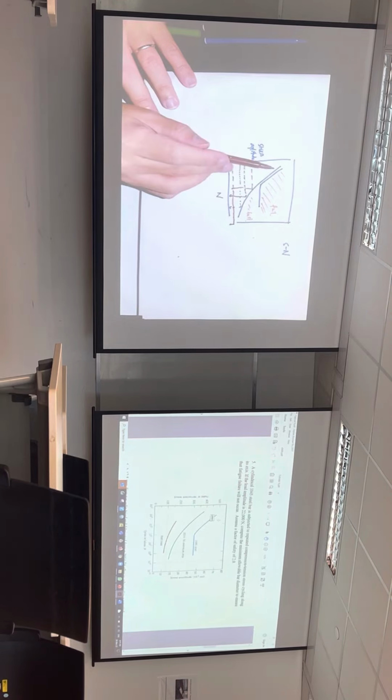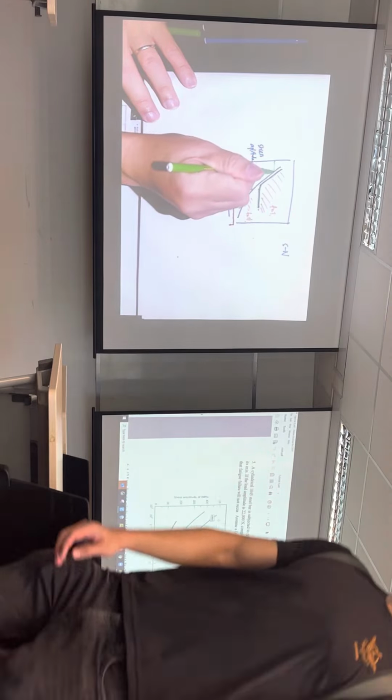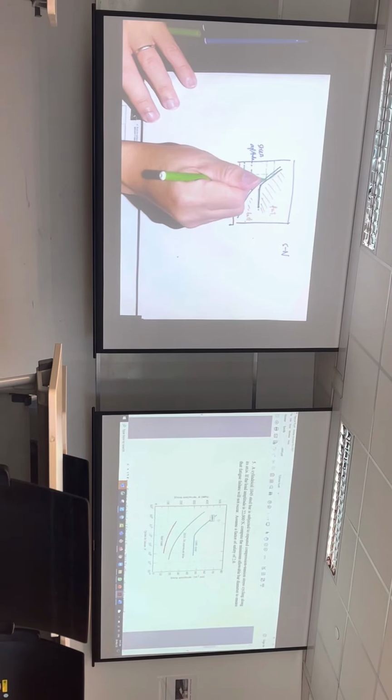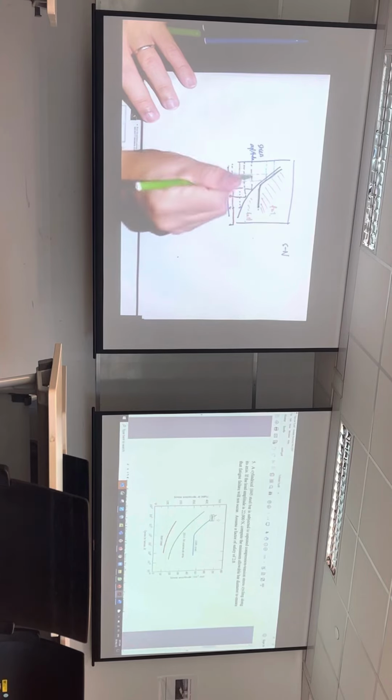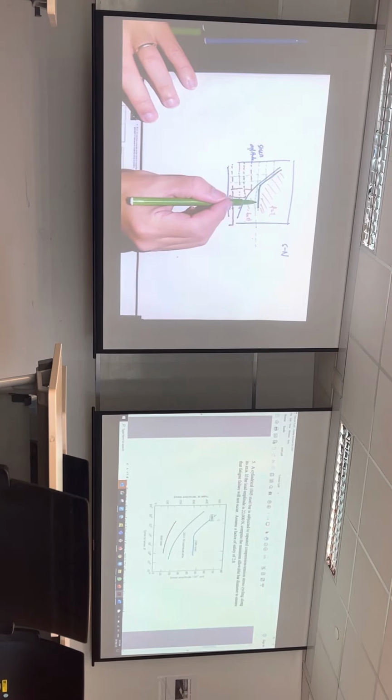So this is for such a material, and typically such materials are like aluminum. So there's no safe area. But if you look at this other material, which I drew in a slightly different color, green: if I work at this high stress, it will definitely fail. If I go over here, it will fail at this cycle. But if I operate below here, it will never fail. So this one has the so-called fatigue limit, so it's safe.